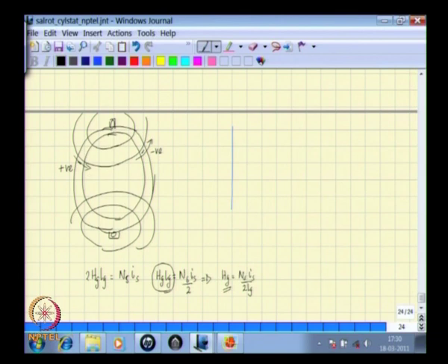So if you draw this at any angle along the circumference of the stator or the rotor, any loop that you take will always give the same equation. For example, let us say you take another loop here, it would still give the same expression, the same Hg into Lg. At this point we have said that the flux travels normal, so Hg into Lg, and then again Hg into Lg in absolute terms should be equal to that.